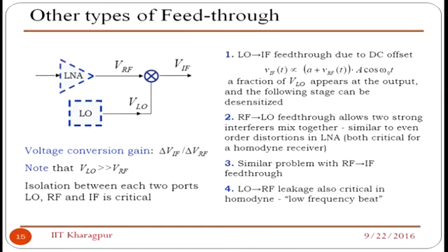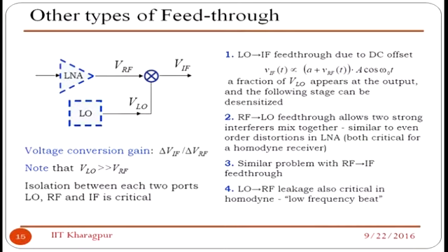Now I am coming to a very fundamental thing which somebody raised about isolations. In active mixing, this isolation becomes an issue. If you look at the expression of your switching or square wave, you have a DC part. Remember, you have a DC component plus cos omega 0 t, cos 3 omega 0 t, all the harmonics.